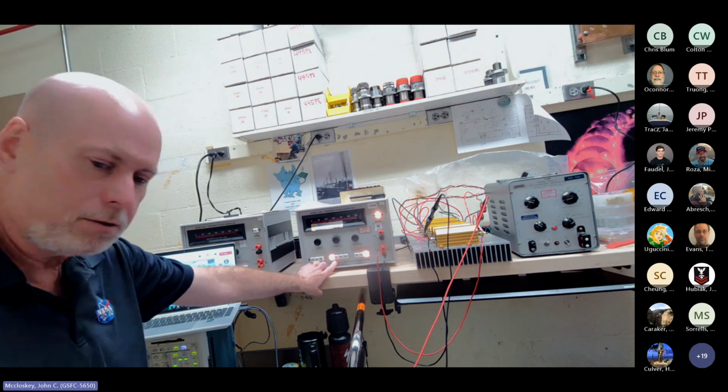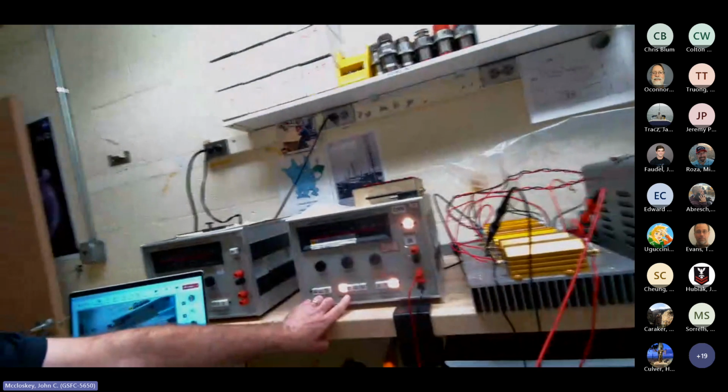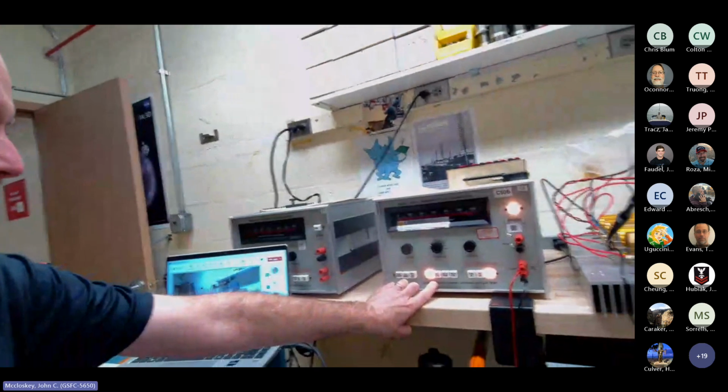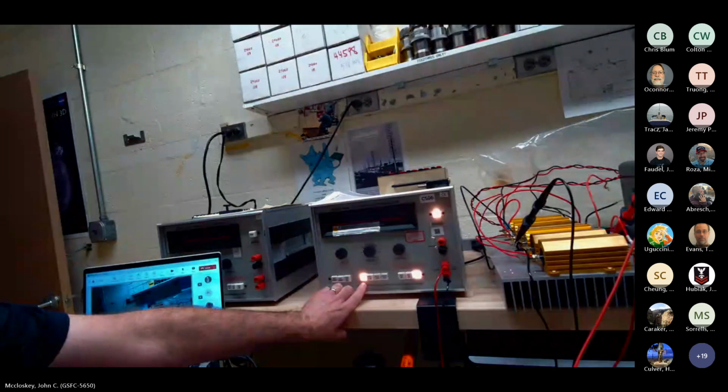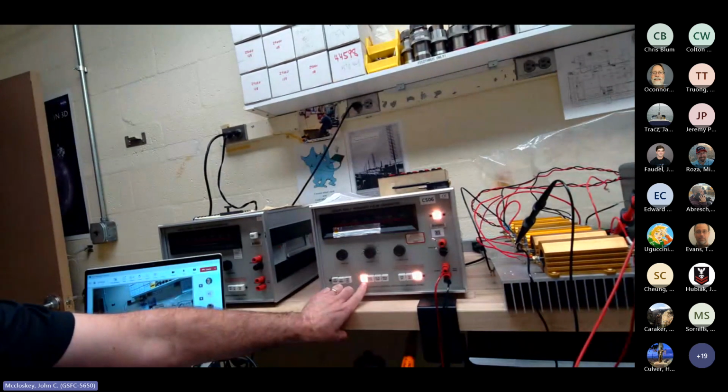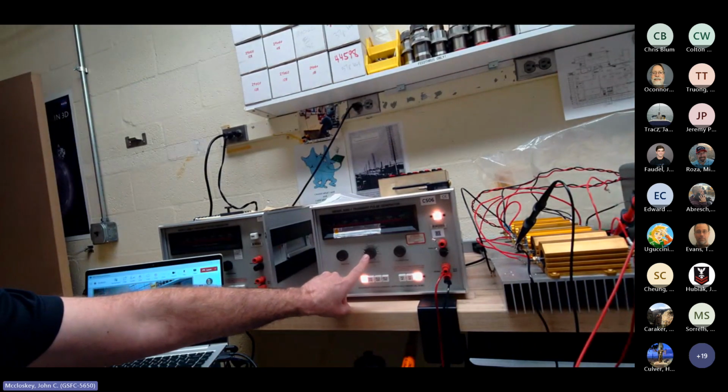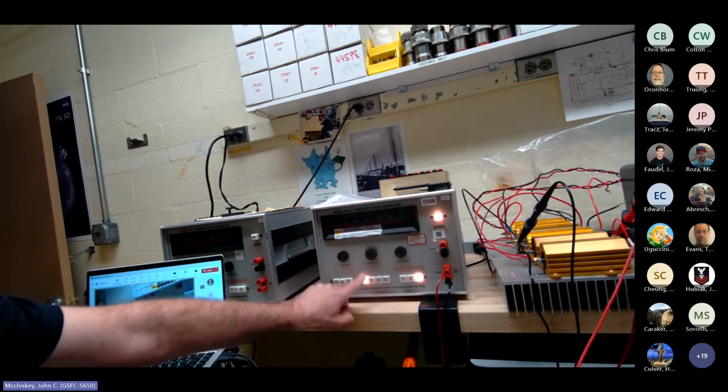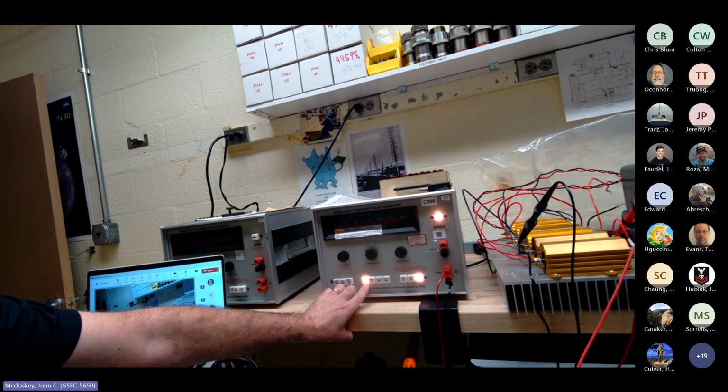This set of switches here, you move this in. This is just setting the multiplier for your repetition rate. This first one's just ×1, and then this is where you're actually setting your repetition rate. So it's just set for 1 and ×1, so just 1 pulse per second. And then the next one over is PPS ×10. So if I just hit this switch, it'll go from 1 pulse per second to 10.